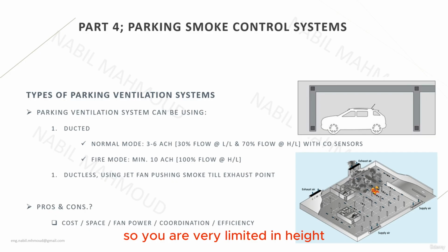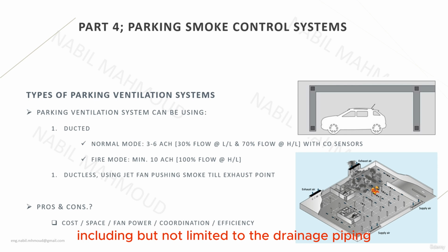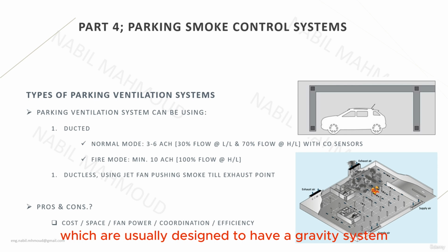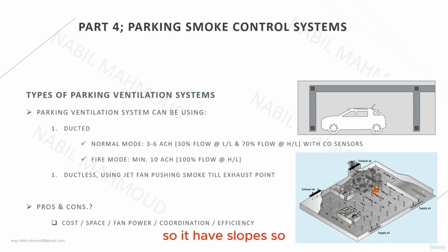So you are very limited in height because you also have other services, including but not limited to the drainage piping, which is usually designed as a gravity system, so it has slopes, so it is very difficult to maneuver around the drainage piping inside the parking.